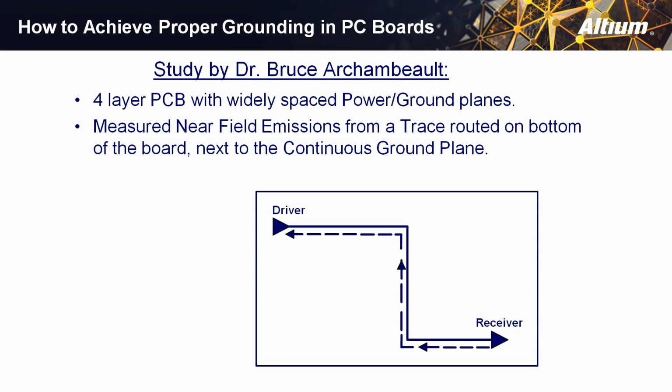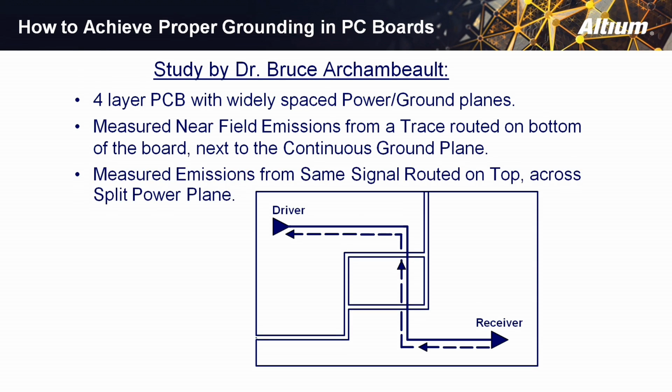Using a near-field probe, he measured the energy radiating off the board. Again, he used a near-field probe because he wanted to be able to get the maximum sensitivity reading of how much energy was coming off of this board. He then turned off this driver and receiver, turned on an identical driver and receiver on the bottom of the board that happened to route across a split power plane. And he then fired that up and made a second measurement of EMI coming off the board.